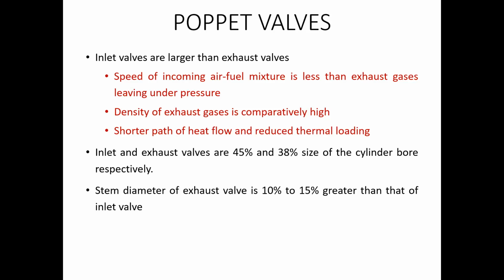Even though air fuel mixture is taken in, the speed compared with the exhaust gas is less. So in order to admit more air fuel mixture in the case of a petrol engine, or more air in the case of a diesel engine, a larger area is required. That is one of the reasons why the inlet valve is made larger.